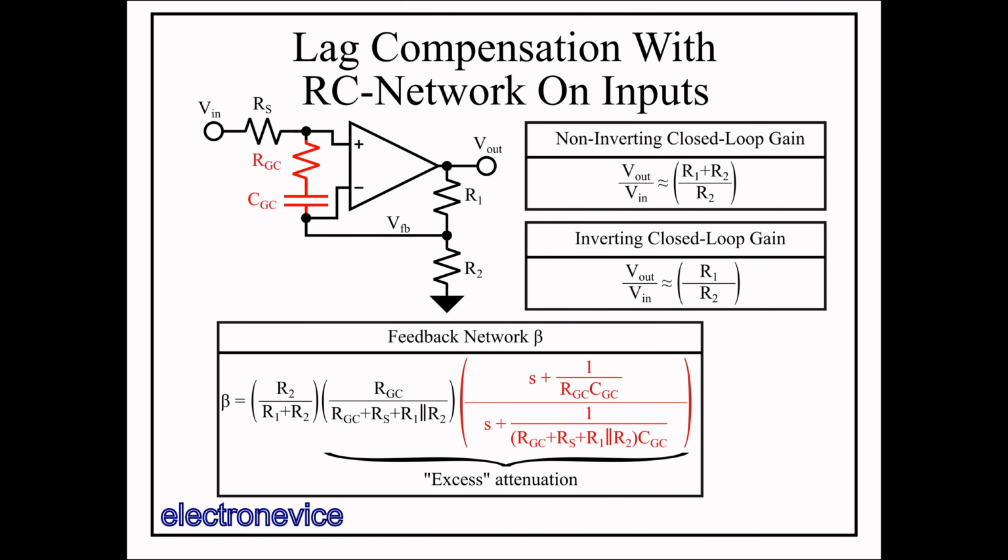Other networks can be put in between the op-amp inputs, and one wonders how well a resistor-inductor circuit would work for high-frequency op-amps, since it would produce a high-frequency zero. You just have to be mindful of magnetic coupling when using discrete inductors in close quarters with sensitive analog circuitry.